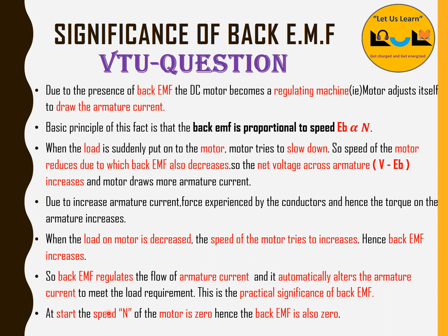At start, the speed N of the motor is 0, hence the back EMF is 0. At starting, the speed of the motor is 0 because initially the motor is at rest. When we give supply, the motor starts to rotate. Whenever it is rotating, the back EMF also starts to increase. So when the motor speed is 0, the back EMF is also 0. As the motor picks up speed, the back EMF also increases. This question, the significance of back EMF, has been asked many times in VTU exams, so it is very important. I mark it with a star.